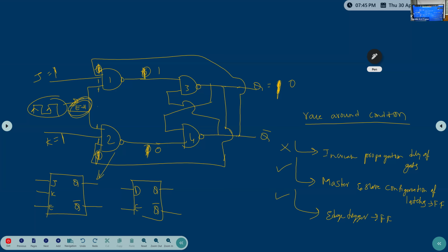And one more question. In the chip, which type of flip-flop will we use? They will ask in the VLSI chip, commonly which type of flip-flop is used? JK, SR, D, T. Four options. Which one? D. Why D? Why data flip-flop? For data storage. Which flip-flop?